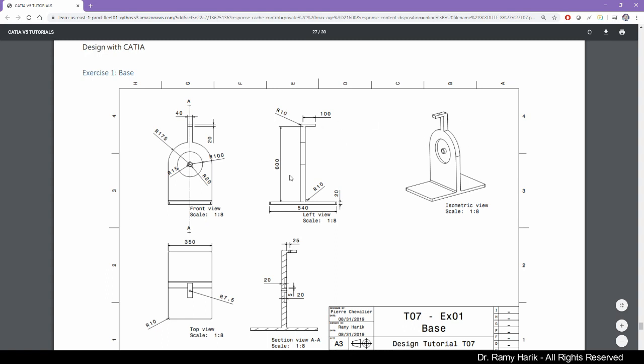Let's see the dimension, the thickness. Where do we see it? This is a 20. This is a 5. No, this is a 5 here between these dimensions. So in here, it's a series of centered circles of radius 15, radius 20, radius 100, and radius 175 for this. This dimension is 40, so we can get away with making this a complete circle if we wanted, and then cancelling it, or we can just build that profile.